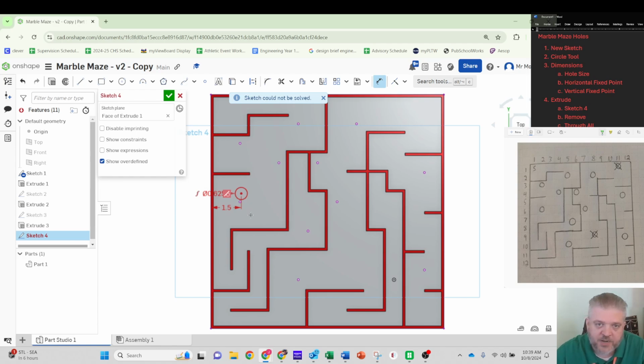So you notice here I got an error. That's because I locked down this circle based off of another one of the walls or one of the other points. So I'm going to go ahead and undo. It happens. So I need to be careful when I make my circle. See right here, the wall at the very bottom is highlighted in yellow. I want to make sure that's not happening. So circle here, 5/8 of an inch.